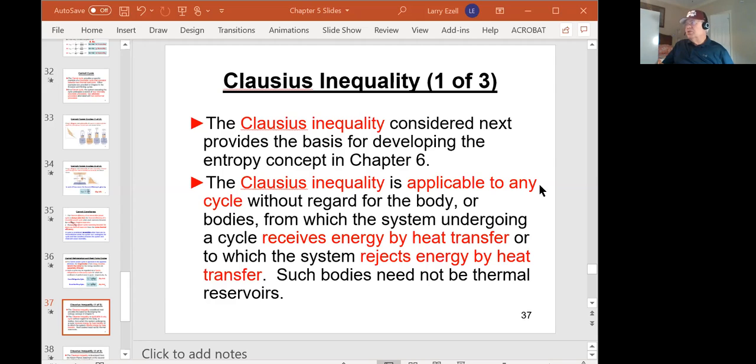And then if it got cool outside or cold, it automatically switched to the heat pump. Now, if it got below 35 or so degrees and the heat pump started to lose its ability to operate efficiently, then you always had backup resistance heating. That's just I squared R heating. That's just putting a current through a resistor and getting the heat and putting it out into space. And that's when your electric meter, that little round thing, would zoom, zoom, zoom when you're in that mode. Okay, enough of that.